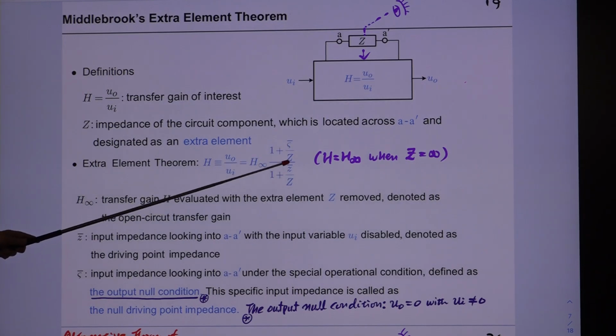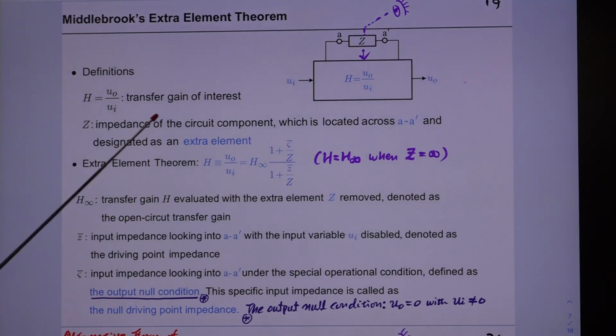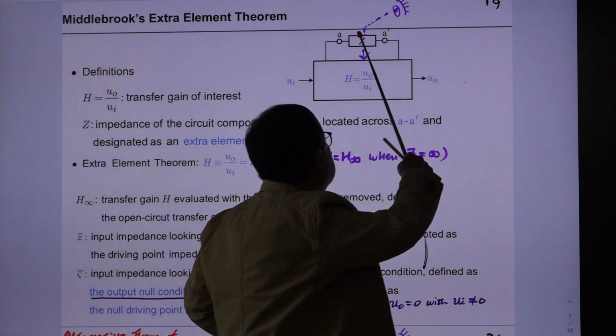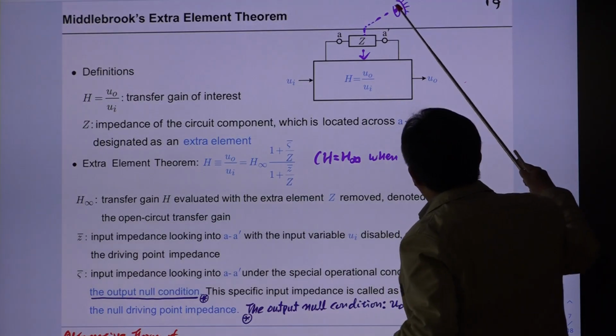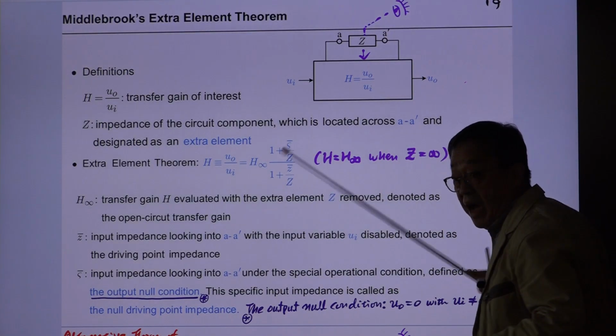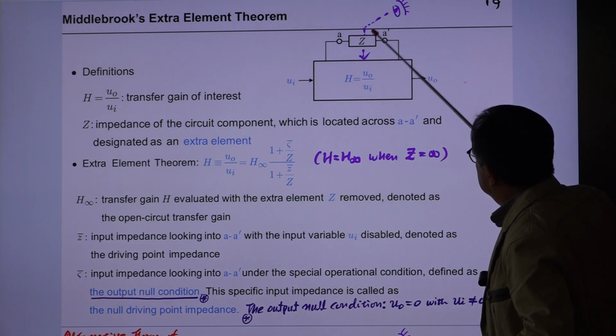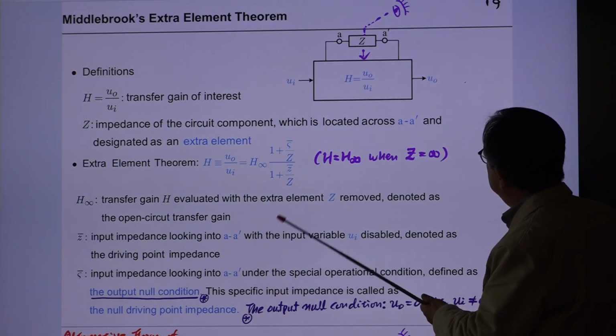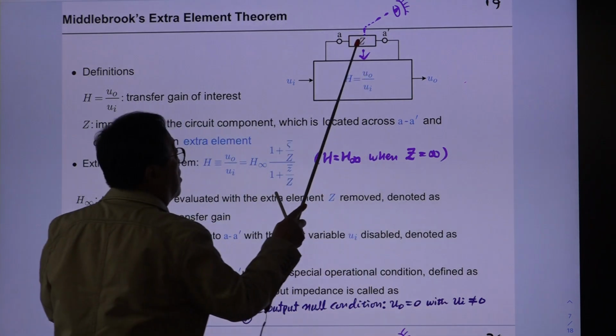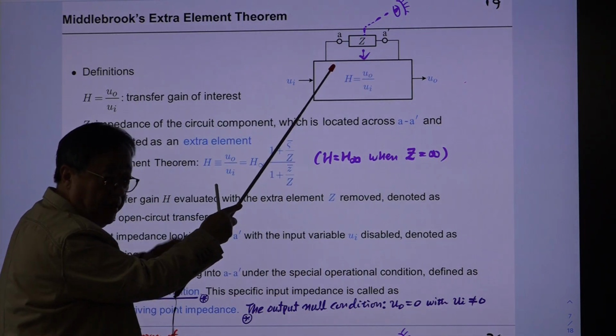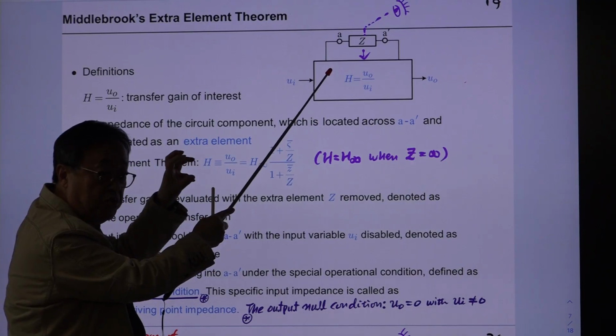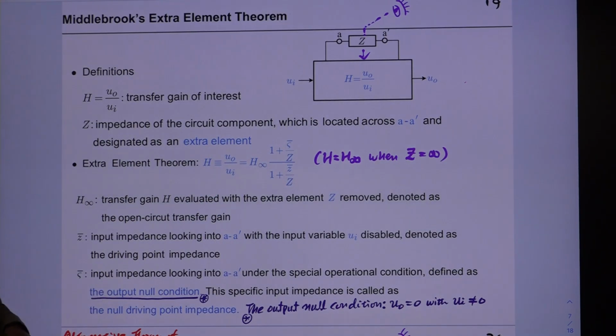Right? There are two impedances. This zeta bar and the G bar are impedances looking into this through this port. Okay, so you are looking into this box through this port, and this is the driving point impedance. Maybe you put a current source here, then measure the voltage across it, and find the ratio between them. That is what? Driving point impedance. Evaluate at two different conditions. One is this one. This one is easy.